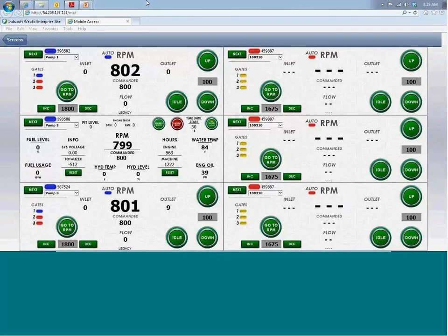One of the other driving factors in choosing the IWS system, InduSoft Web Studio, was the HTML5 compatibility. The system that we had developed prior ran solely on Flash, and as some of you are aware, some mobile devices don't technically run Flash. So the way that this customer was starting to evolve was the fact that they wanted to use tablets and different things, and they're migrating from a ruggedized laptop in the tractor cab to tablets and smartphones and all that other stuff.